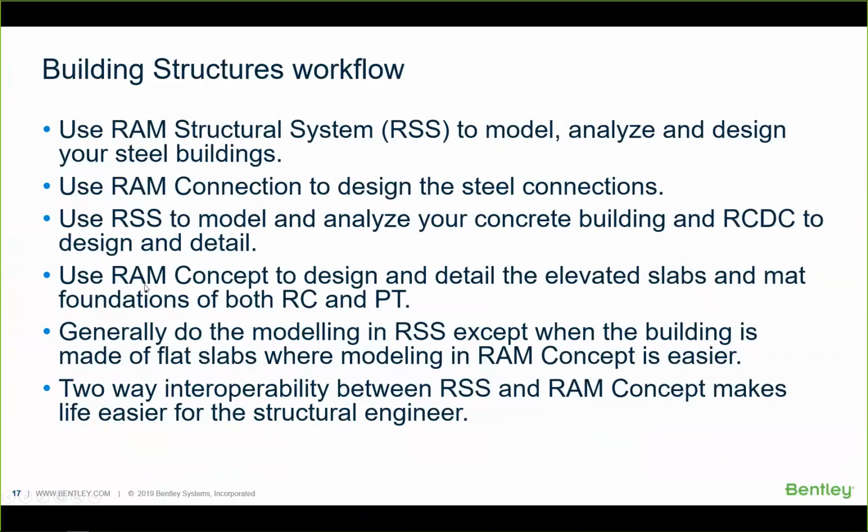And finally, RAM Concept is useful for designing the slab as well as the mat foundation, both reinforced concrete as well as the post-tension slab. So for slab design, we have an overlap here. RCDC also does the slab design. RAM Concept also does slab design. But in addition to slab design, RAM Concept does mat foundation design also, which RCDC doesn't do.